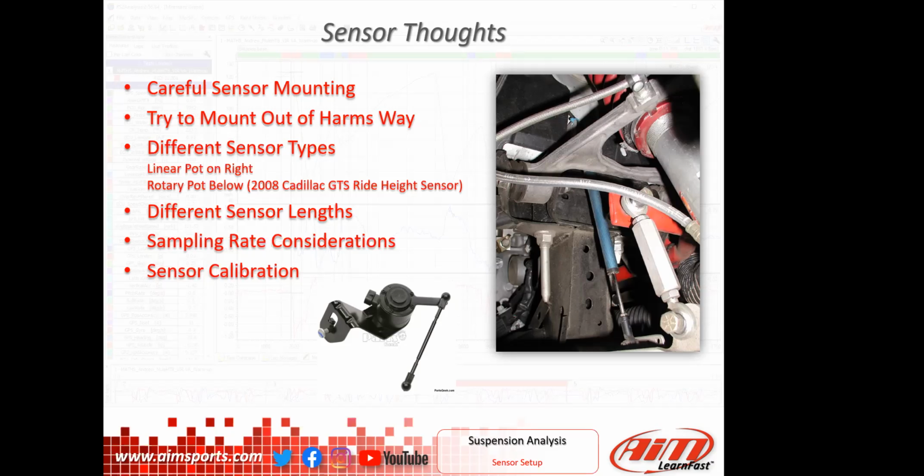The baseline that a lot of people will say is maybe 200 samples per second. 500 is what your AIM systems will do, and 500 is probably what any number of people will use. And I know when I've done some work with some folks doing NASCAR type circle track stuff, where they're taking that data right into some of the computer programs that they use to prepare their cars, we had to do them at 1,000 samples per second, because that's what that particular hardware and data pieces they were taking the data into really worked at.